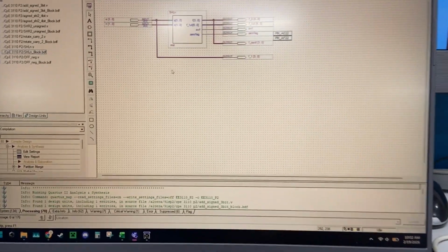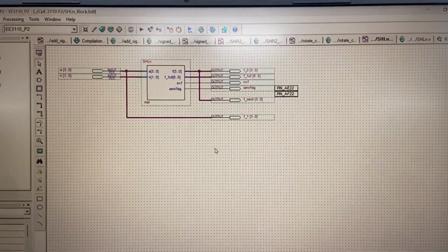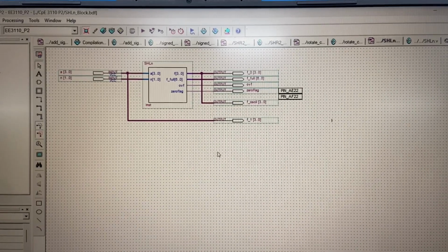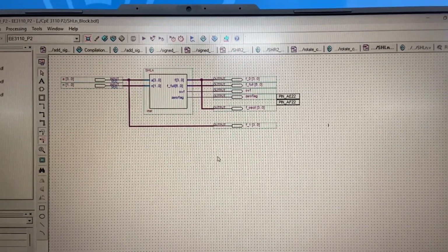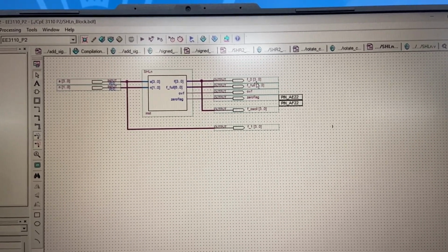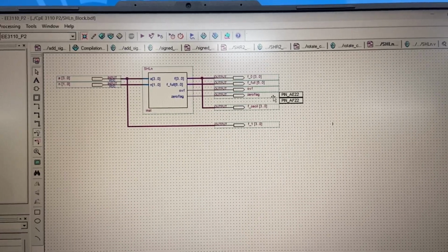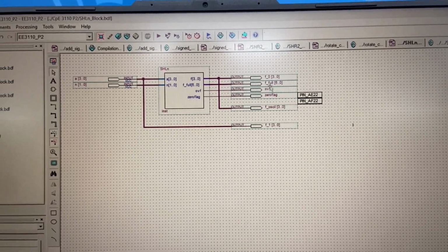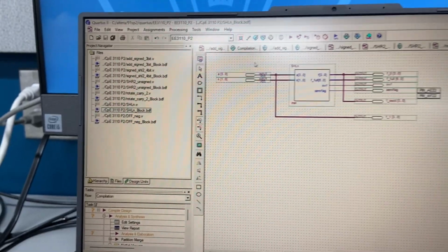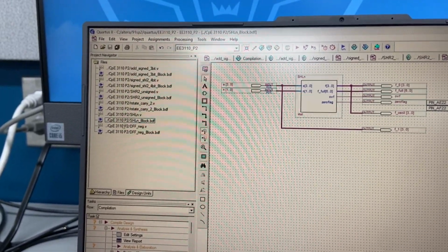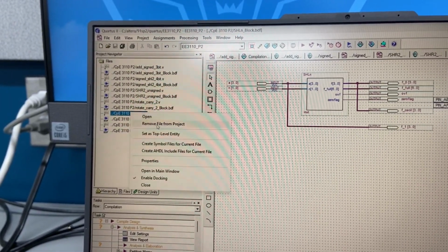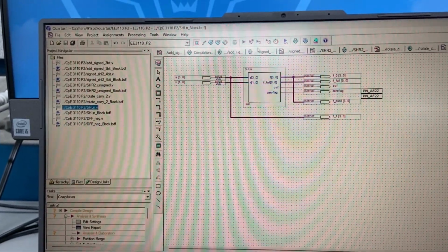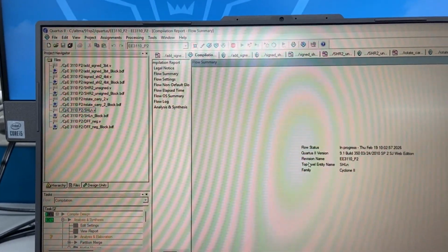So this is the block right here where we have a 4-bit input, 2-bit shift input. We have our F output, the F full, the overflow, and the 0 flag outputs, the oscilloscope output, and then the input as an output to determine time delay. And I'm going to go ahead and just recompile this just to make sure that we get the correct RTL.